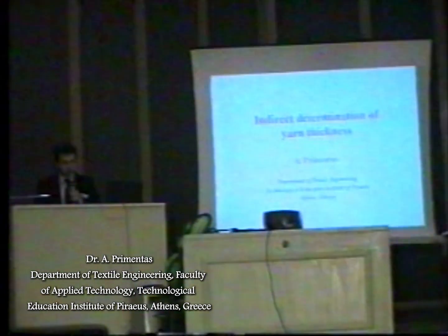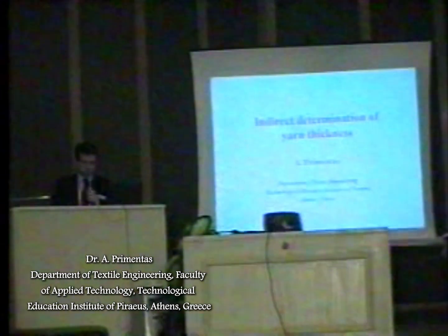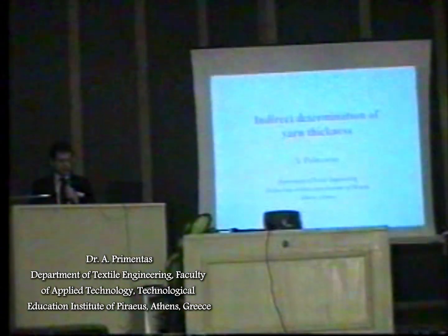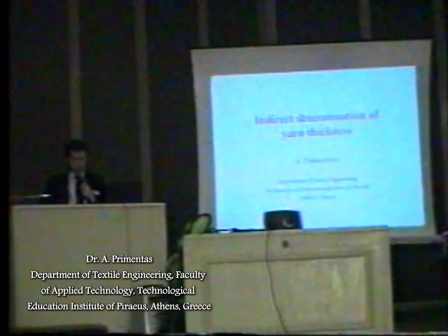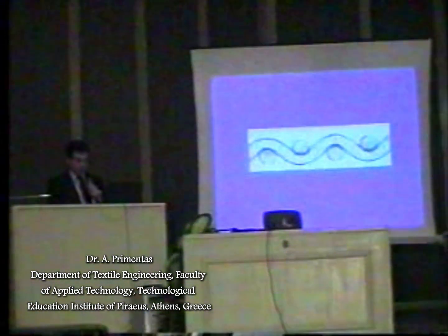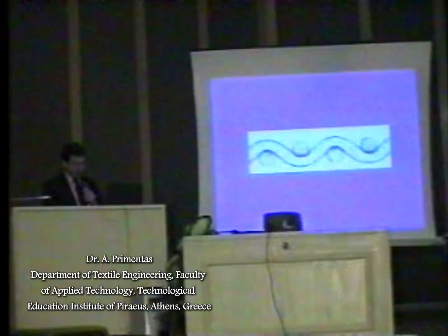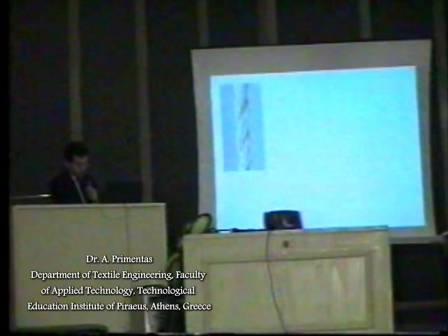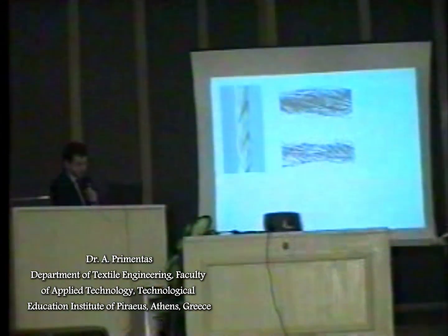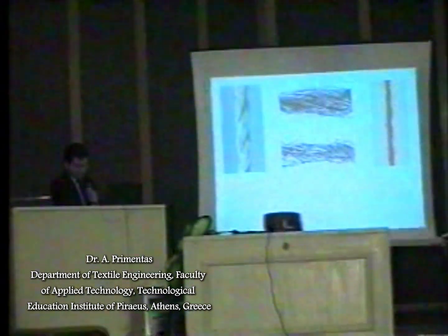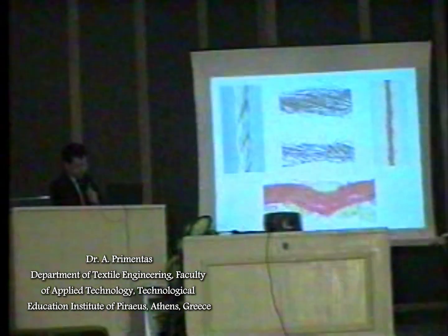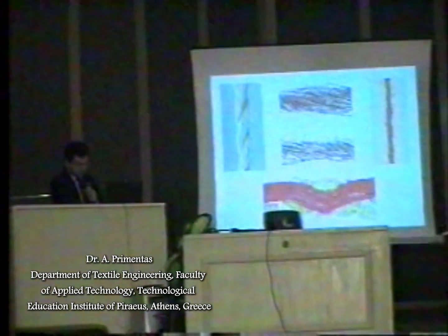In the idealized yarn geometry, where the yarns have a cylindrical shape with a perfect circular cross-section, the measurement of their diameter could be made simply by observing the yarns or the woven fabric cross-section under a microscope. In practice, the twisted ribbon-like form of the yarns, the shape of their irregular surface where thick and thin places appear, their hairiness effect, as well as their compressed status in the woven fabric structure, prevent the determination of its thickness / diameter.